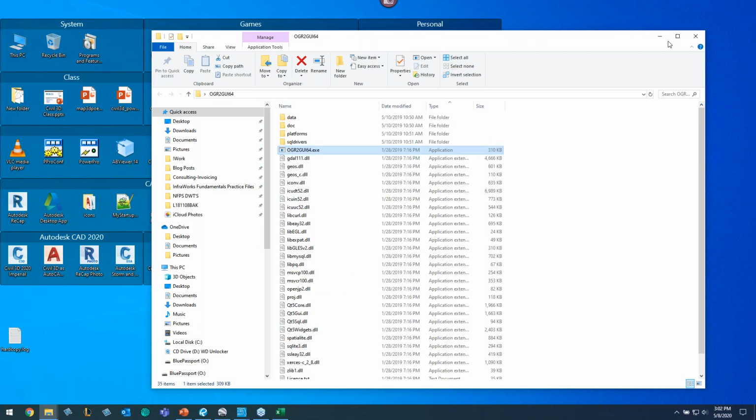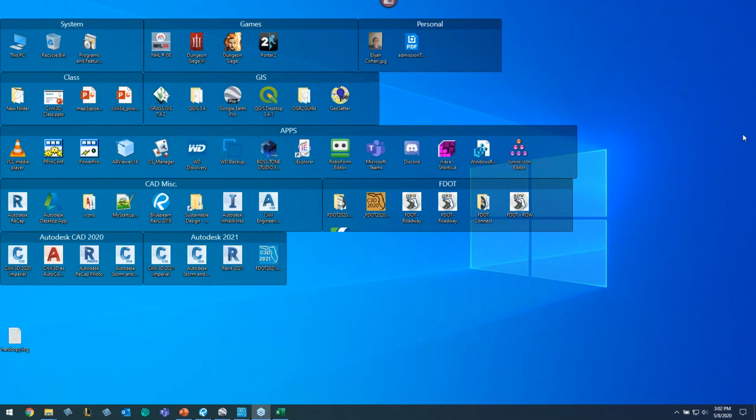Thank you, Seth. The same person that asked the question about the CH space command wrote again that in paper space, you can do the rectangle in the viewport and bring this into model space. Okay, so he's talking about change space, CH space, yes. That command will work, but if you have your viewport and you draw right on top of it, it's actually not going to matter. You're still going to need to scale it up. I know what he's asking now.